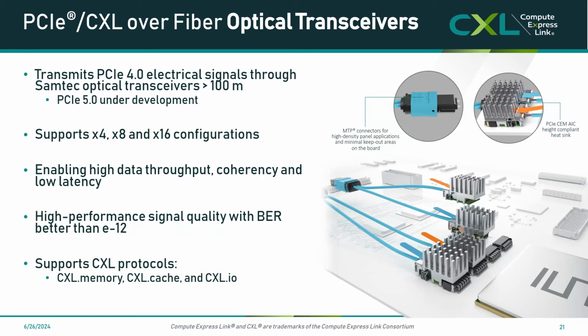To delve into this a little bit more in terms of PCIe/CXL over a physical layer optical interface, we actually have a family of optical transceivers finely tuned for the PCIe infrastructure that CXL sits on. So we have a family of PCI Express focused optical transceivers which comply with the physical layer and electrical signaling defined by PCI SIG for PCI Express, enabling you to do E to O and O to E over 100 meters.